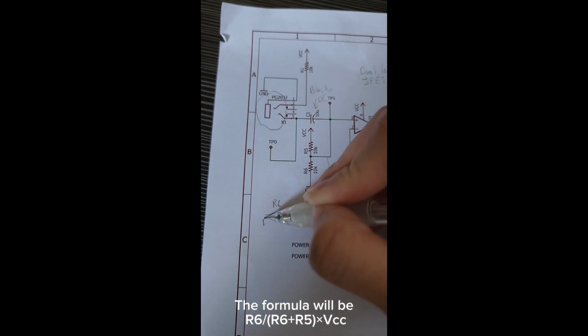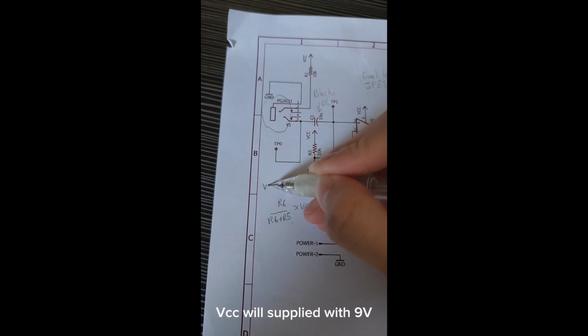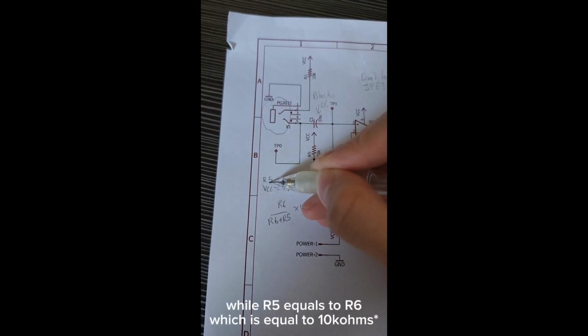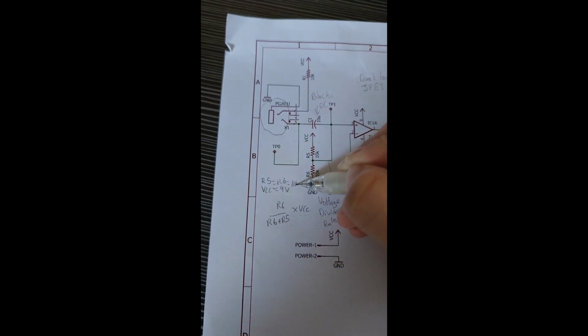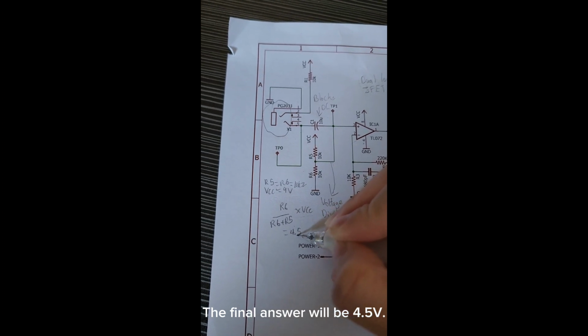The formula will be R6 over R6 plus R5 multiplied by VCC. VCC will be supplied at 9 volts, while R5 equals R6, which equals 10 kilohms. The final answer will be 4.5 volts.